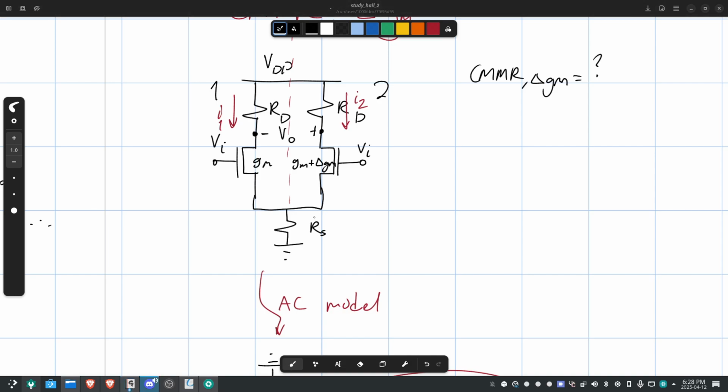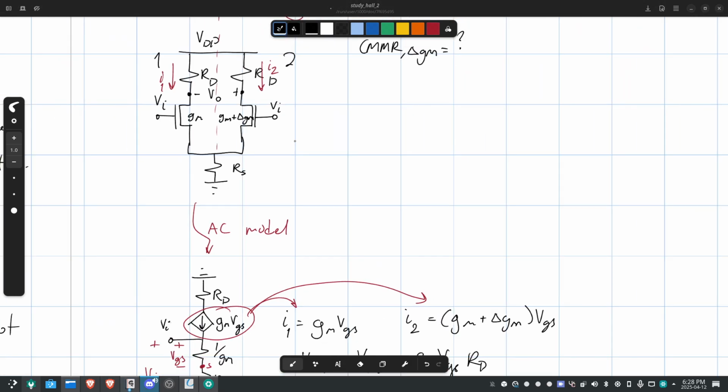RS here, right? How do we split this up into two pairs? Because this is sort of combined. Well, remember, we're working in common mode. So this connection splits. But we can't exactly split this connection, right? Because there's still this kind of RS in the way here. We can split RS in two. We can remove RS and create two RS here and two RS here. Thank you so much for pointing that out, because I forgot about that.